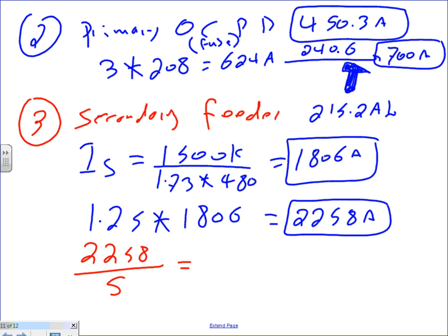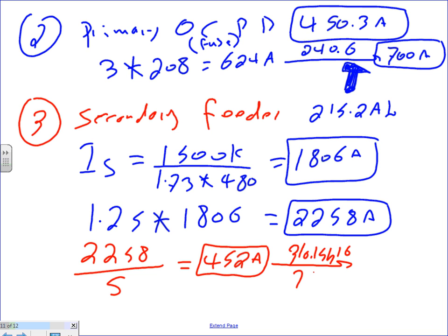This will give me 452 amps. Now you know why I parallel 5. Why the 5? Because it gives me 452. And if I take this to 310.15(B)(16) under the 75-degree column, now actually this is a low voltage conductor, right?